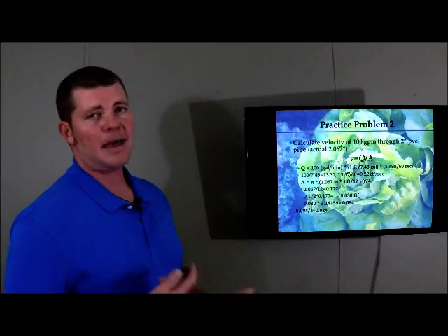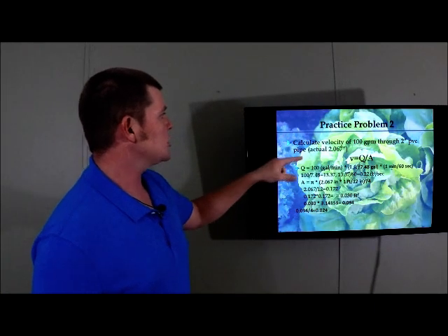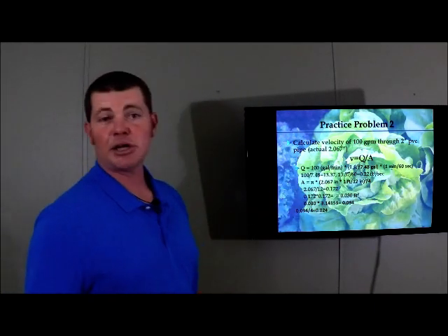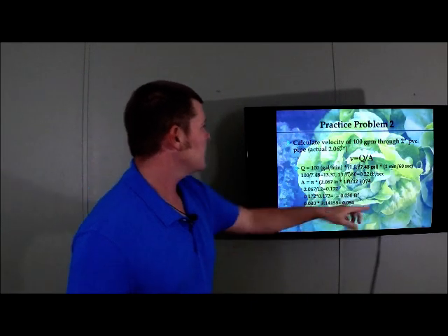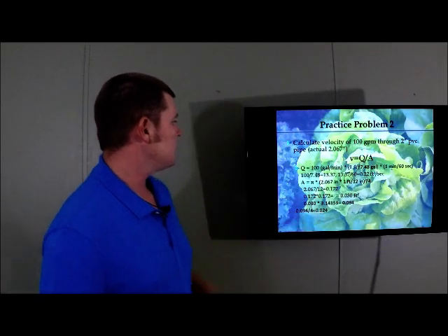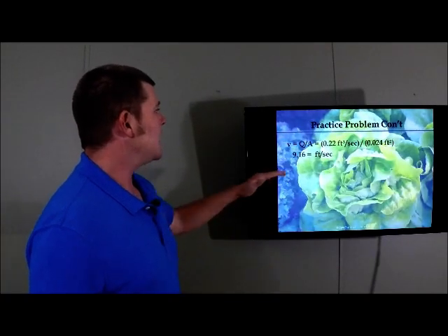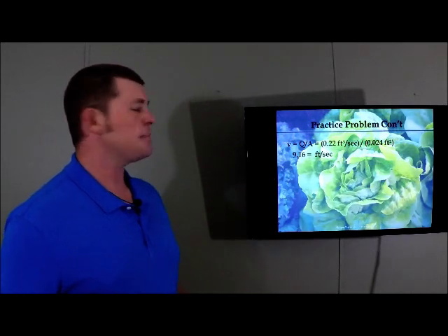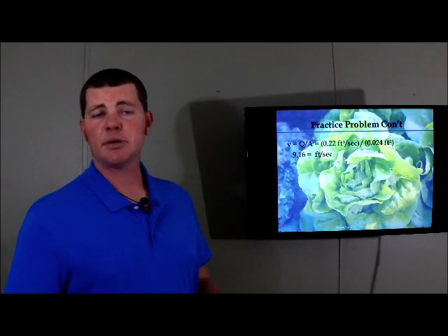And we've got a lot of math through this session, so this is the exact same math we just did. We just used 2 inches instead of 3 inches. So we'll kind of go through this, but the numbers we get, Q equals 0.22 and A equals 0.024. When we do the division, we get 9.16 feet per second. I think there's a clear winner between 2-inch pipe and 3-inch pipe.